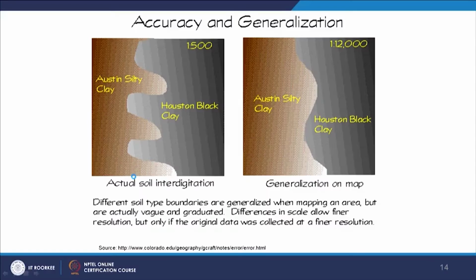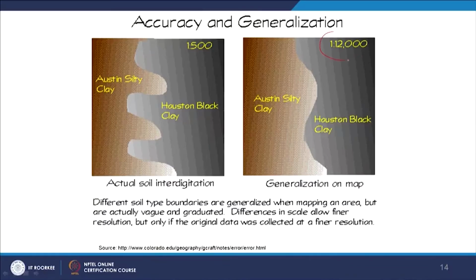Of course, when you attempt generalization, you are compromising with accuracy, and that is why I am saying do not delete your original data, which may be more accurate than your generalized data. So, always have a backup of that one, and then you can perform and use it. Generalization depends on scale also. At this scale all details about the coastal lines are here, but at this scale I do not want those details, so I will perform the generalization.